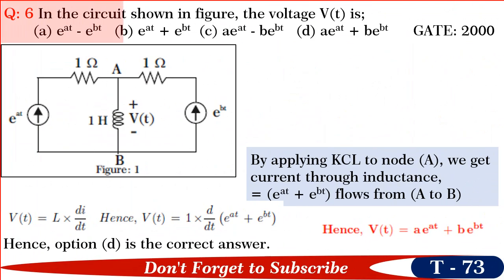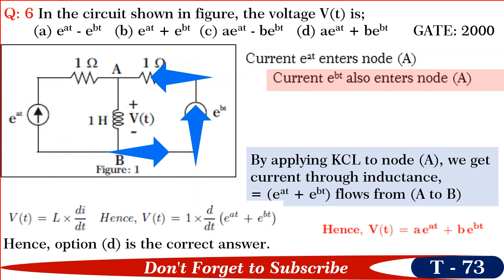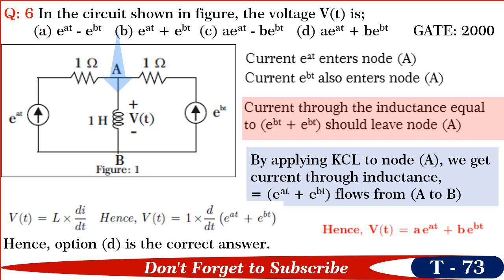Friends, next we shall solve GATE question of 2000. In this question, we are required to find the voltage V of t across the inductance in the network given. Observe the network. Current e to the power of at enters node A and current e to the power of bt also enters node A. So, current through the inductance equal to e to the power of at plus e to the power of bt should leave node A.